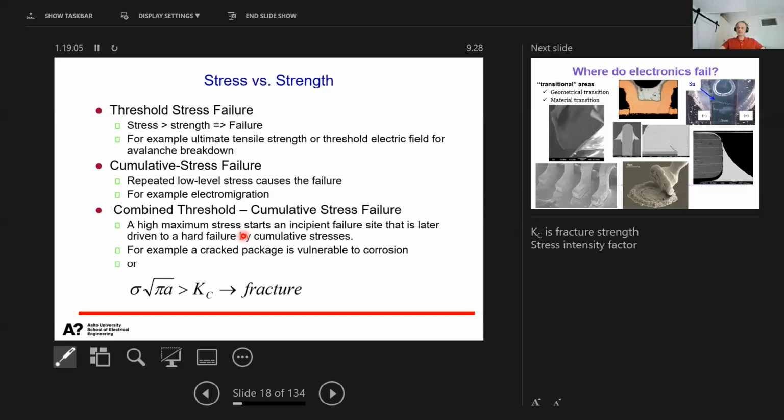Or, maybe a pen example, you leave this one outside. So there's UV radiation, and the polymer is very sensitive to UV radiation because the UV cuts the bonds between the polymer chains. And when this pen stays outside in the sunlight for several weeks, it gets weaker against mechanical loading. Okay, so maybe again, a self-evident thing.